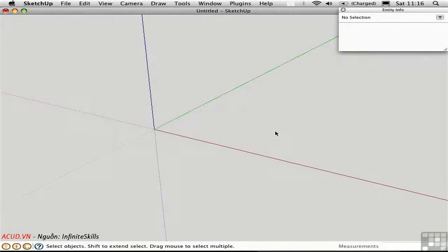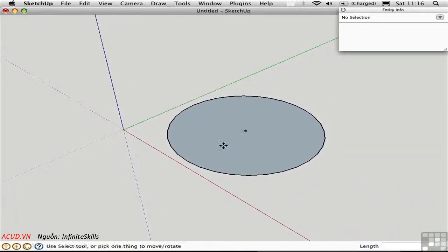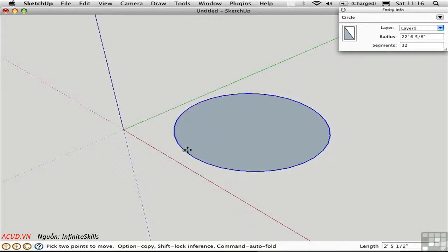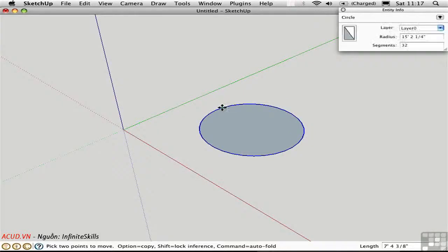Circles have handles on their quadrant points, which allow you to resize them. I'll draw a circle over here, and I'll switch to the Move tool. If I grab the circle from some arbitrary point along the edge, I can just move it. If I grab the circle from one of its quadrant points, these are the 4 cardinal points, like north, south, east, and west. And they line up with these endpoints here. They're not on midpoints. If I grab it from a quadrant point, I can then resize the circle. And that works on all 4 quadrants.